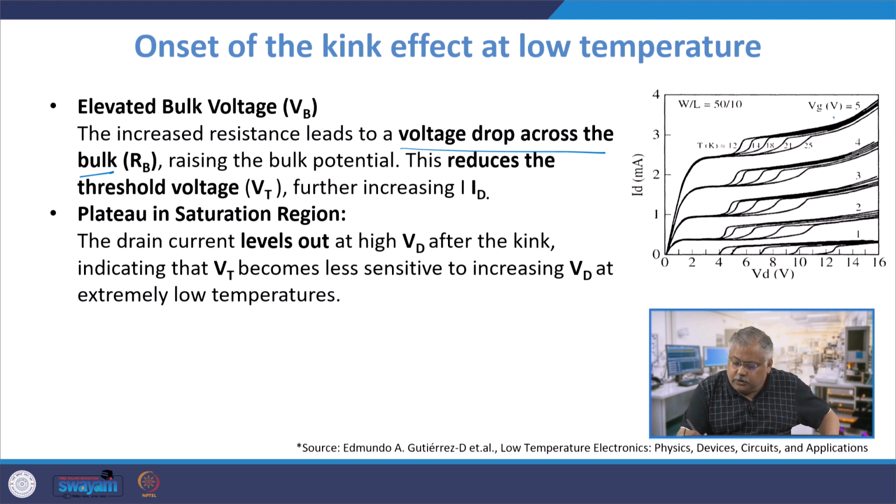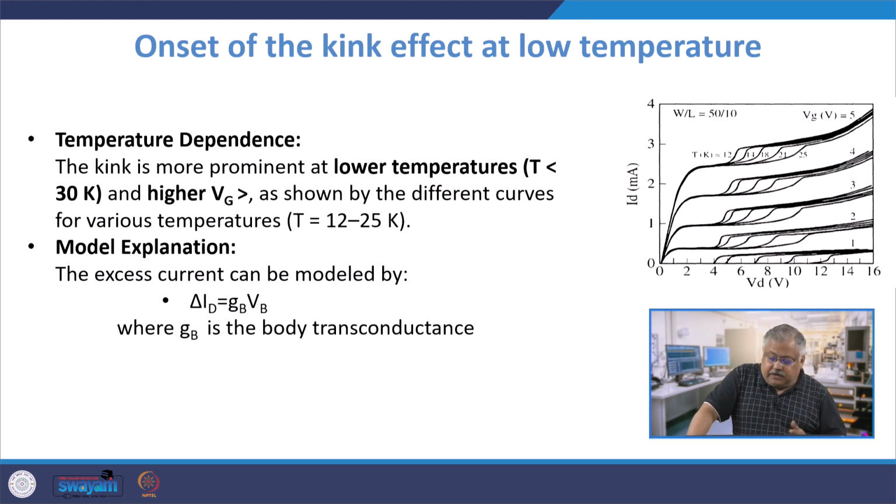As I say, they all tend to sort of bunch together at extremely large values of VD. Now the temperature dependence, as I told you, is that the kink effect is more prominent at lower temperatures and higher gate to source voltage, obviously at higher drain voltage as well.